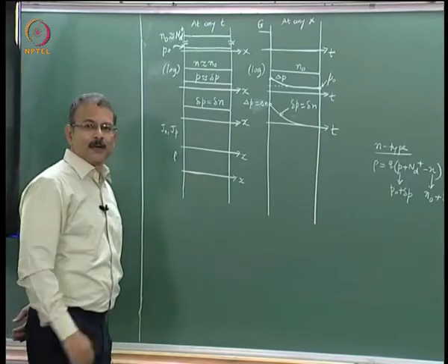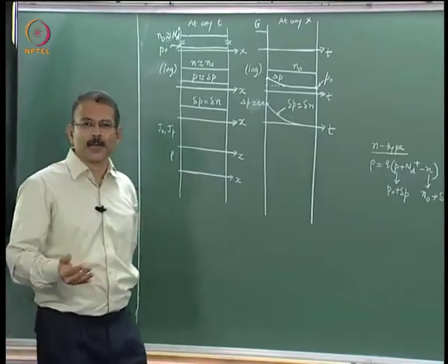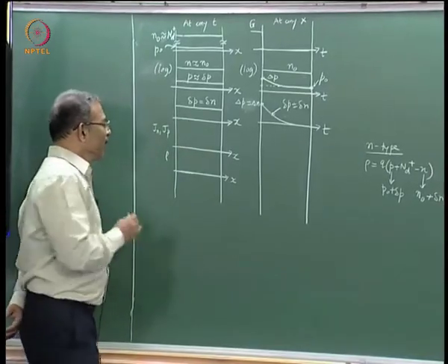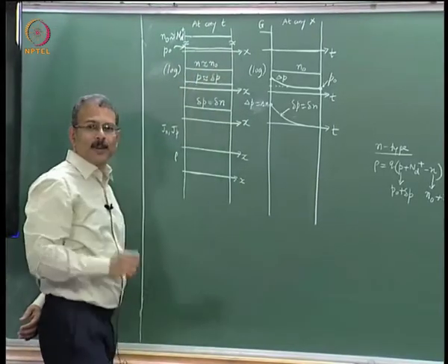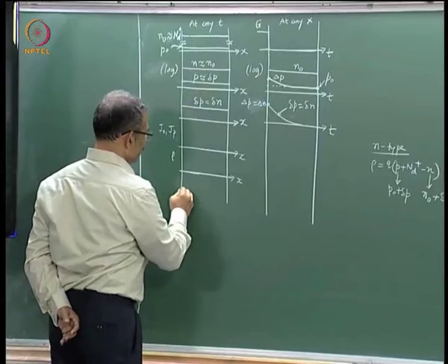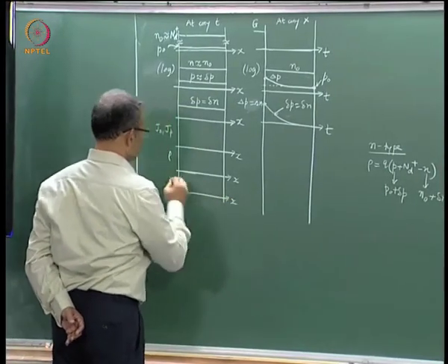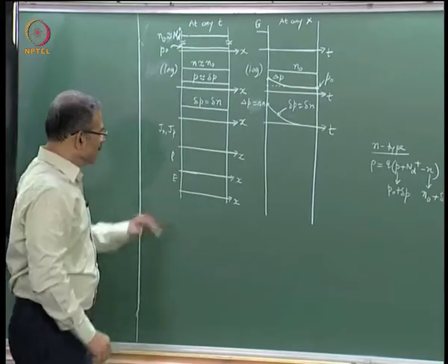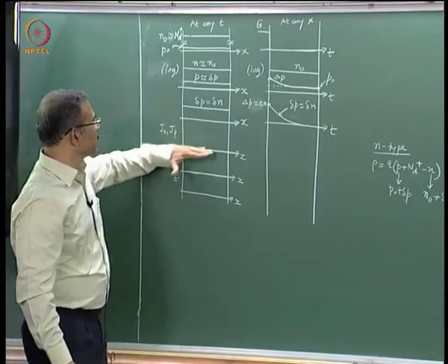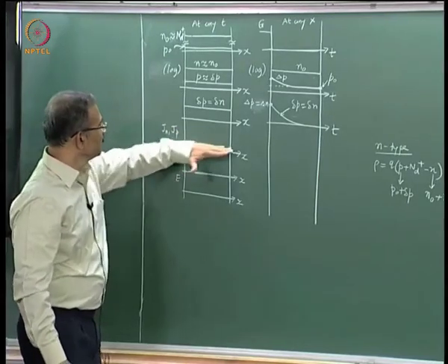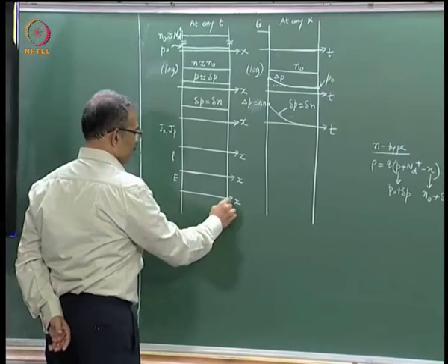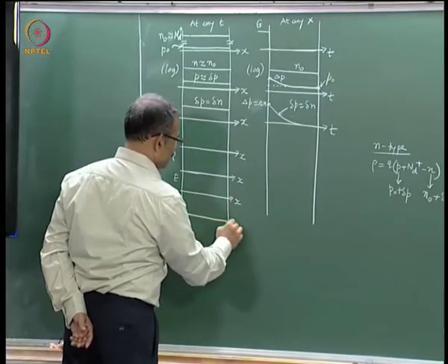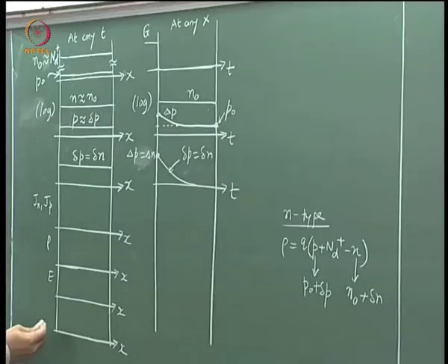Now if space charge is not there, you know the electric field should be constant by Gauss law, but there is no electric field either at the left end or at the right end. There are no surface charges, nor have you applied any electric field, therefore the electric field is 0. Since the electric field is 0, you know that electron and hole currents are also 0. So here all these lines will be just the x-axis. Psi, since there is no electric field, the potential is not changing, so we can assume the potential to be 0 everywhere.